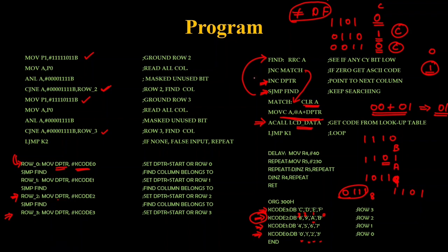So I am going to create a delay. I have said that the delay should be 20 milliseconds, so you can make use of a timer for creating a 20 millisecond delay. You can use any timer mode to do that operation. Else, if that is not needed, you can use a simple timer in terms of iteration. We have seen many things with respect to timer. You can create a delay without a timer also, but approximately it should be equal to 20 milliseconds.